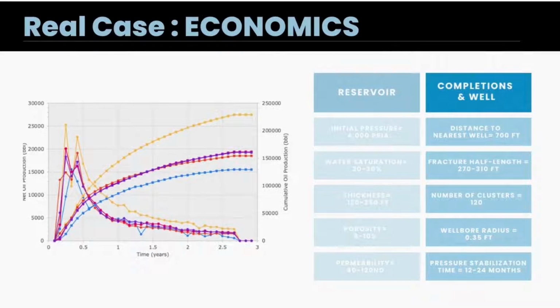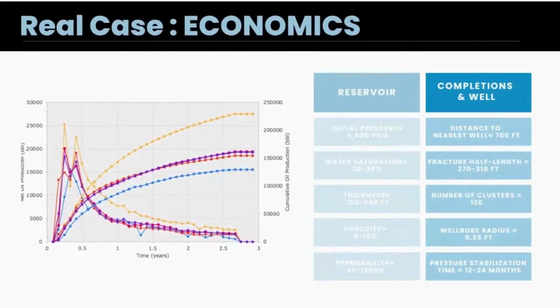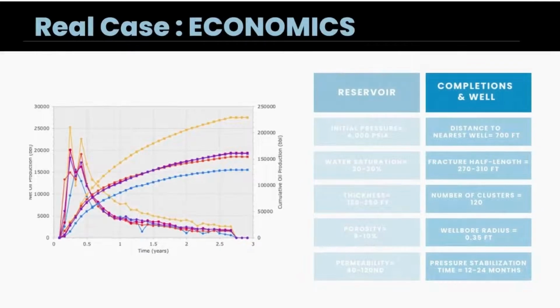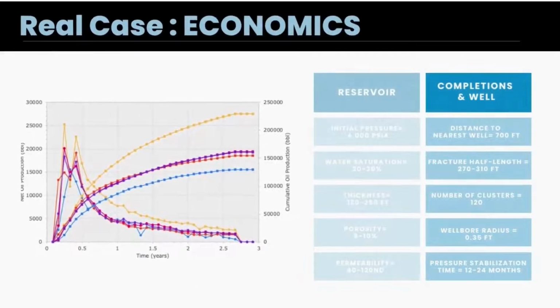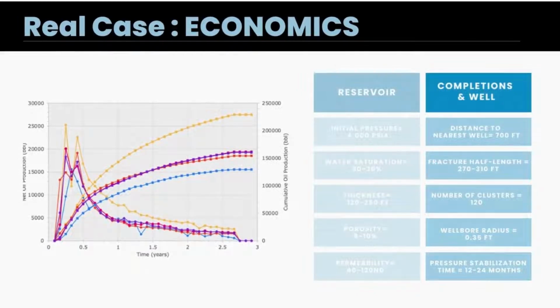So these are the six wells. The six wells were presenting different production variability. You can see it on the left side. The yellow curve was the well that was shorter in lateral length, with fewer stages. The other wells were more alike when it comes down to the completion design. You can see some reservoir properties and completions for the wells that were part of the reality in the asset. They were part of the inputs for the numerical simulation as well.